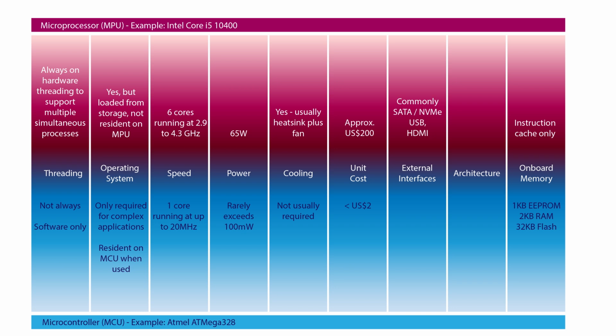The final big difference I want to draw your attention to is how the microcontroller is designed to interface with other devices. Microprocessors use something called a bus architecture. They have multiple input-output pins that connect to 3 buses for addresses, data, and control signals. If you want to control things like relays for lights and to read button presses, you'll need an interface to these devices that is also designed to work with that bus architecture.